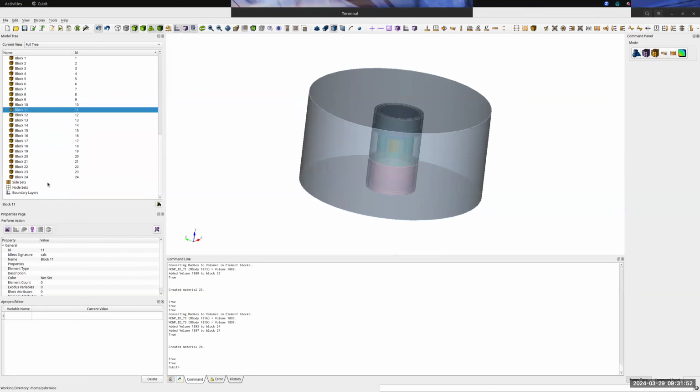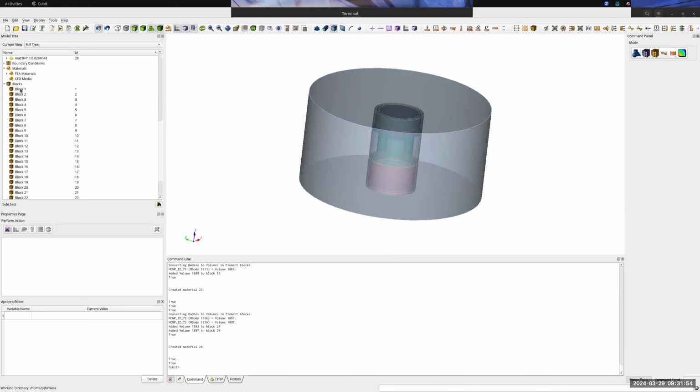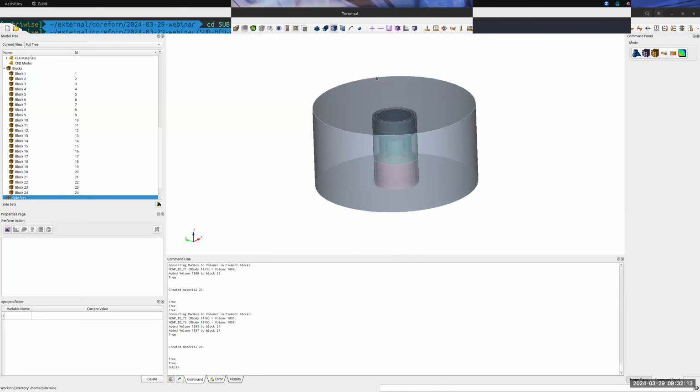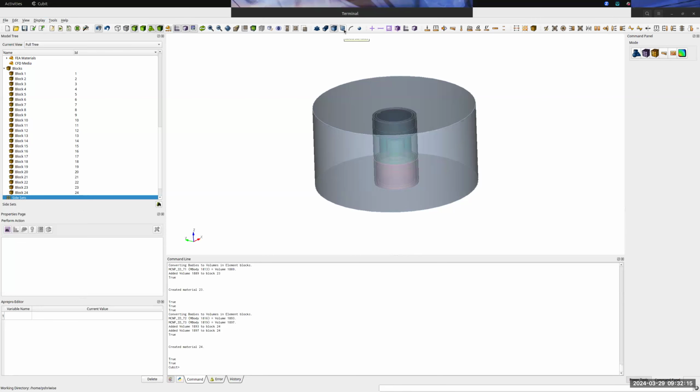Okay. So now that we have our material assignments taken care of, the last thing we need to do for metadata is set boundary conditions. Unlike MCNP, OpenMC relies on surface boundary conditions to define the exterior space, or the endpoint of the physical model. And so we're going to be using that capability today. Let me zoom around a little bit if possible.